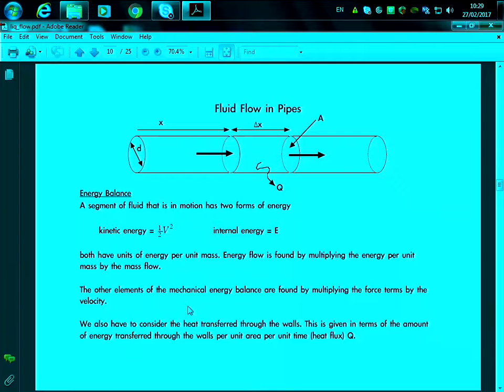Okay, so this is basically just the units of the fluid, and in this case we'll basically use whatever is affecting the system in terms of energy. So what will constitute the energy balance? We have kinetic energy, we have internal energy, but let's say we have a pipe that is not insulated and there is a heat flow between the outlet and the interior, then we'll have some changes of internal energy of the fluid. It will change its temperature because of that. And what else do we have?